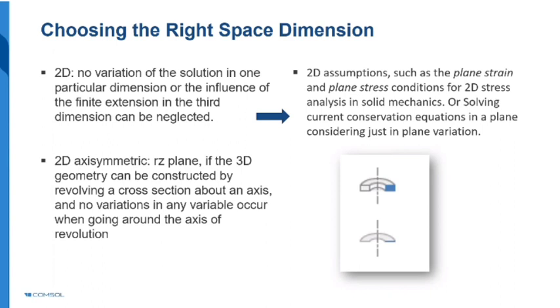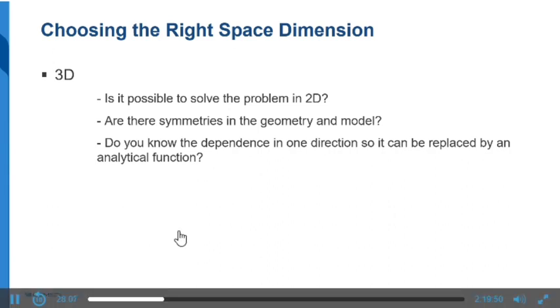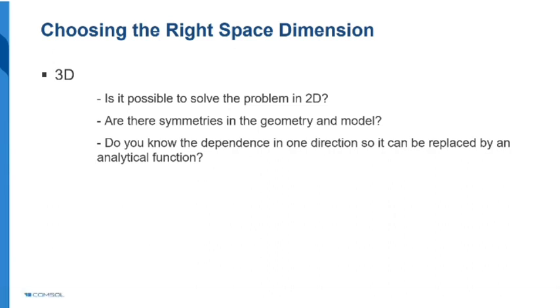But again, over there as well, your boundary conditions and physics conditions should allow you to approximate that problem with 2D, 2D axisymmetric, or 1D. If modeling with 1D, 2D, or 2D axisymmetric is not possible, definitely you can go ahead and build the problem in 3D. But in 3D also, check whether any type of symmetry is possible, that is half symmetry or sector symmetry.